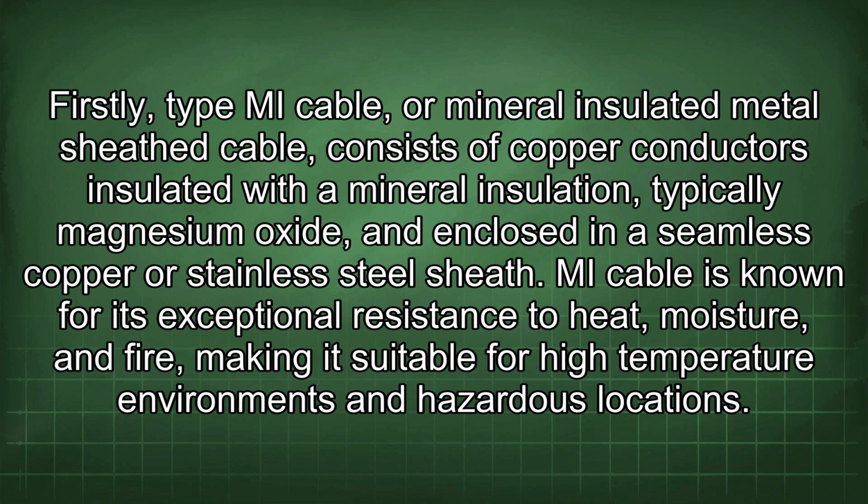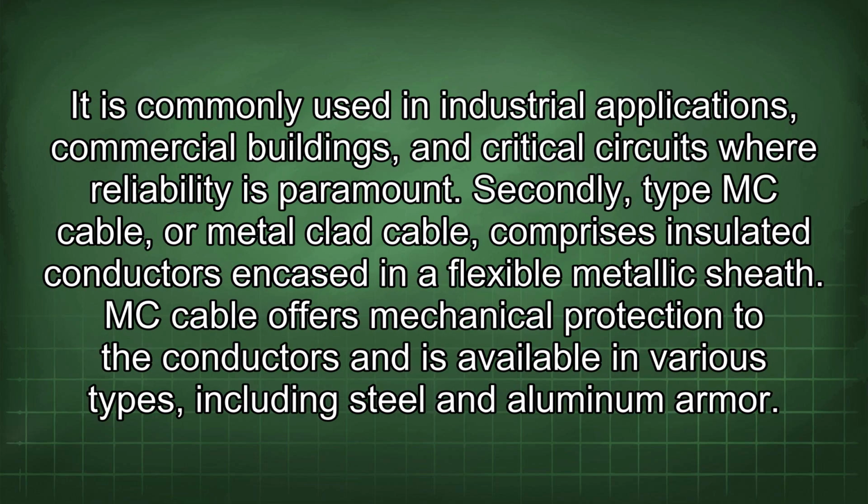MI cable is known for its exceptional resistance to heat, moisture, and fire, making it suitable for high-temperature environments and hazardous locations. It is commonly used in industrial applications, commercial buildings, and critical circuits where reliability is paramount. Secondly, type MC cable, or metal-clad cable, comprises insulated conductors encased in a flexible metallic sheath. MC cable offers mechanical protection to the conductors and is available in various types, including steel and aluminum armor.